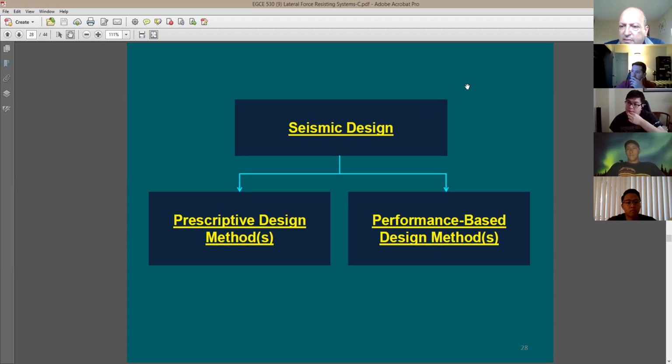this displacement demand, if you like, and find out the strains and the stresses in all the structure members. If the strains and the stresses are within your limits, your design is good. So with this design here, it gives you more chance to control your design and change the members the way you want it.